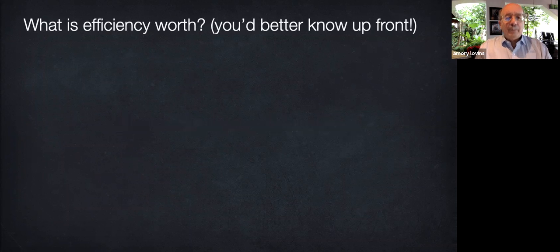A useful first step is to figure out what efficiency is worth and write it on your hand or stick it on your forehead so you won't forget. For example, in a typical clean room, paying 8 cents for a kilowatt hour of electricity, it's worth around $10 present value to save a watt. It's worth $4 per liter per second of exhaust flow to cut the pressure drop by 250 pascals or 1-inch water gauge. It's worth about $150 a kilowatt to make a continuous duty motor 1 percentage point more efficient.